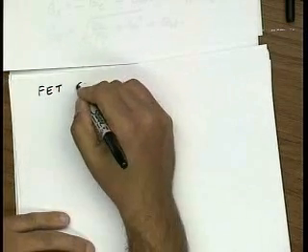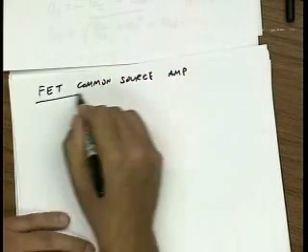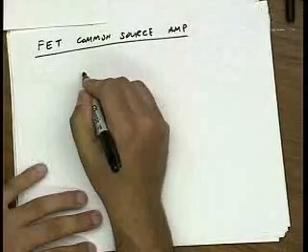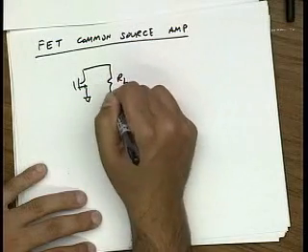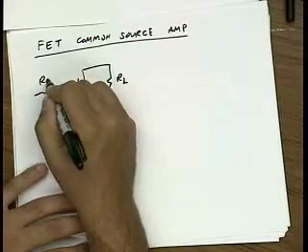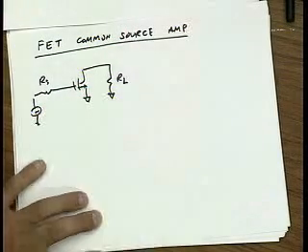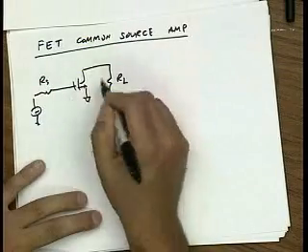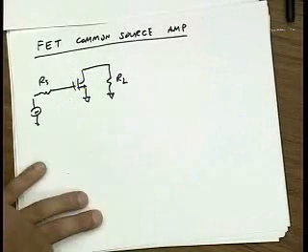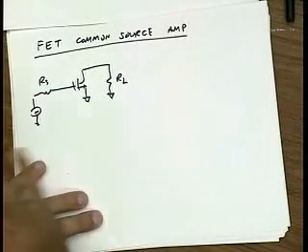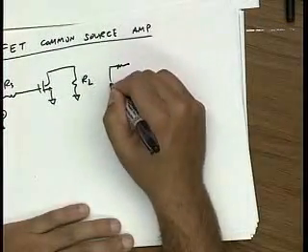Let's calculate the noise of a FET common source amplifier. Very simple calculation. Let me just assume there's RL here, and I drive it with RS. And I want to find the noise figure of this simple circuit. Now, the hard way is to actually find the equivalent two-port representation for this transistor and then calculate Z opt. That's the long way. Let's do it the short way.